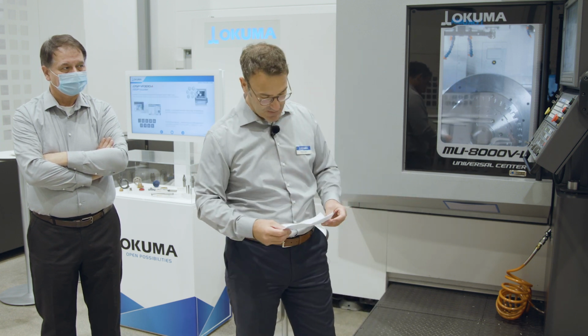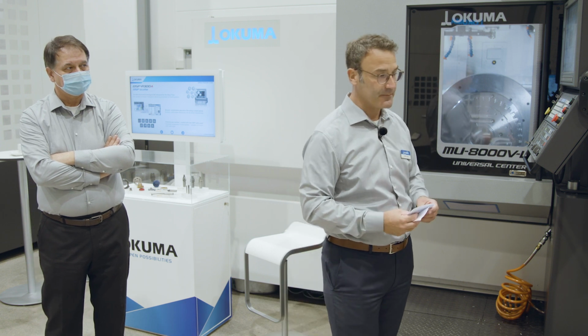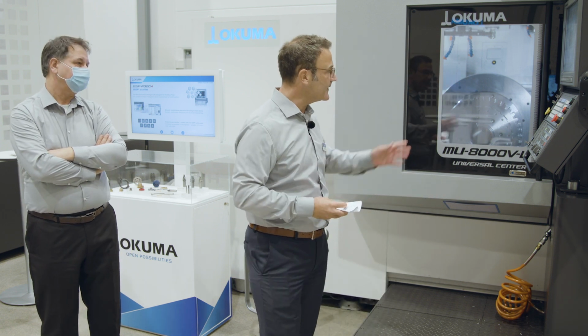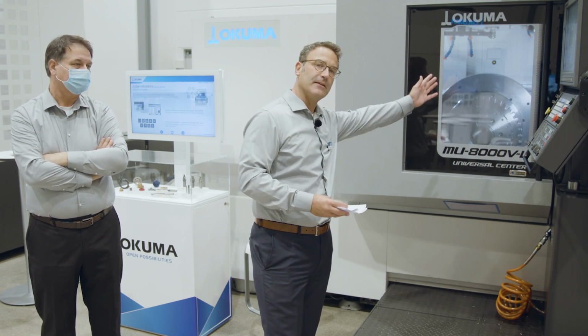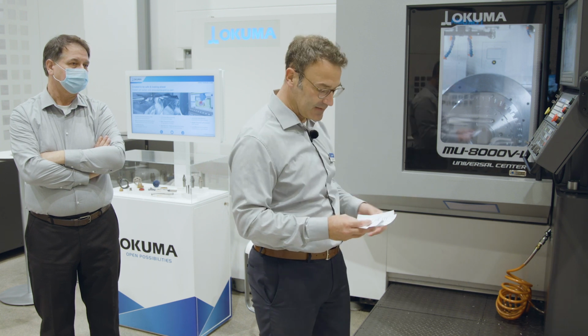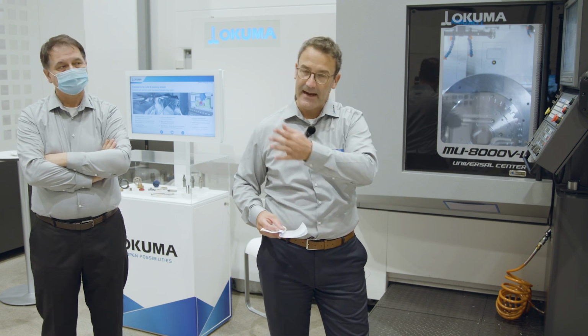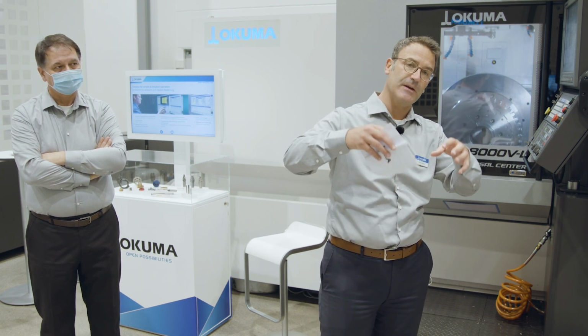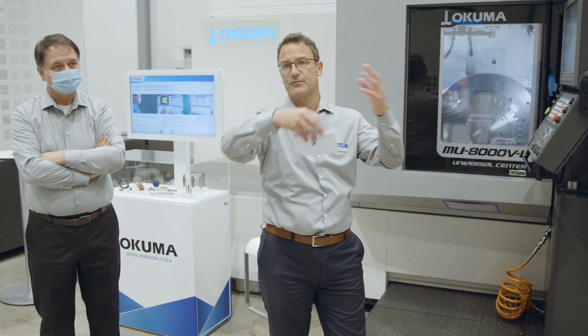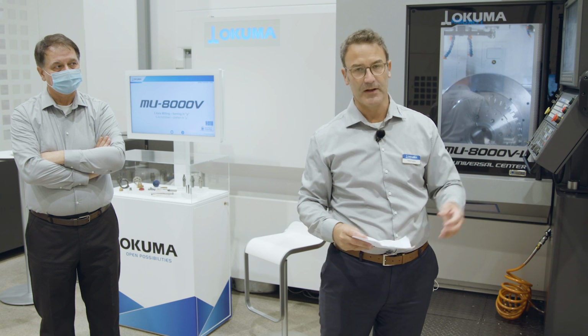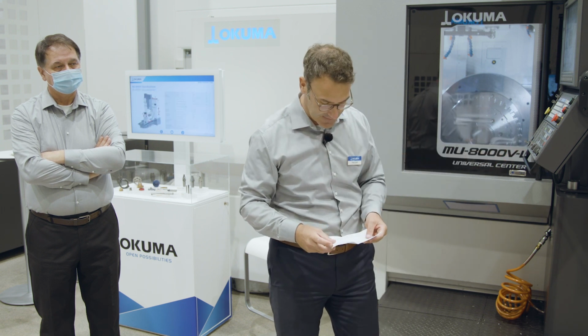What else to tell on that one is, regarding some key figures, we have in X 925, in Y the full range over the table itself is 1050 millimeters. We have in Z 600, and we have the swivel axis, A axis, plus 90, minus 120. So if we have a certain accumulation of chips inside of the part or on the part, we easily can swivel the table with some shower coolant. We have the clean part, so all in all, perfectly designed for unmanned production.